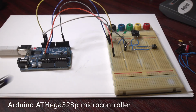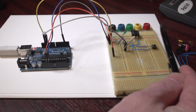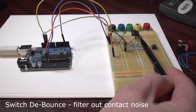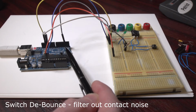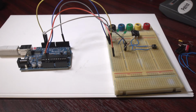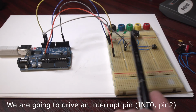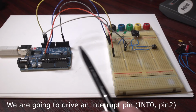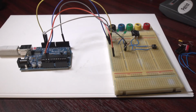a switch, and we're going to be looking at different ways to what we call debounce, or if you like, clean, filter out the signals coming from the switch to drive an interrupt pin on the Arduino. There are different ways to do this. You can do it with a hardware solution, actual components on the protoboard, and you can do it with a software solution where you don't use any components externally for filtering. You do it all in the software. So two different methods, and we're going to be looking at both in this video.